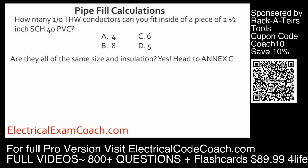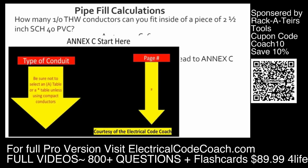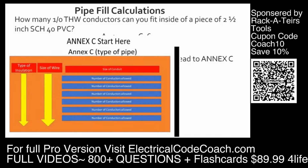Are they all of the same size and insulation? Yes, so we're going to head to Annex C. When we get there, we're going to start on the left-hand side until we find our type of conduit, being sure not to select the A version of the table. Then we come across and find our page number. When we get to the table, we always read the black bold heading to make sure that we're in the right table. Starting on the left-hand side, looking for our type of insulation. When we find it, we go to our size of wire, come across the top until we find our conduit size. Then we're going to come down and tee off and find that we can fit 8 more conductors inside of this conduit. Great job.